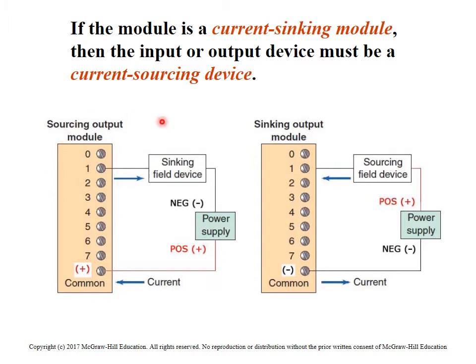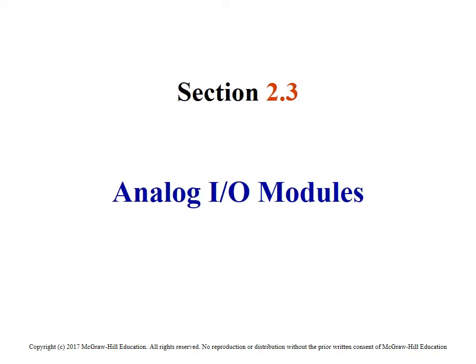Most of your wiring in this case is going to be a sourcing output, and your inputs are always going to be sinking. So keep that in mind. That's the most common anyways. There's a couple of manufacturers that do have sourcing inputs where you have to have a negative power to them, and the only one that I can think of offhand is the Motoman robots.